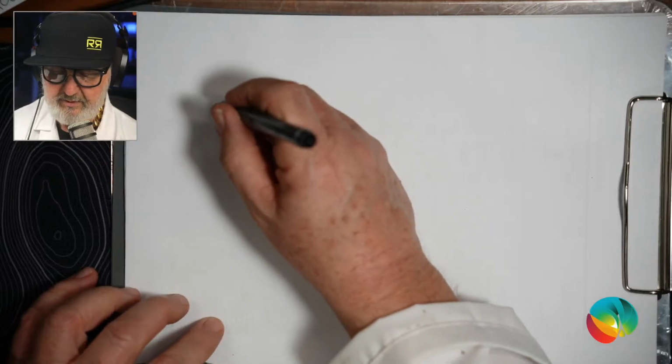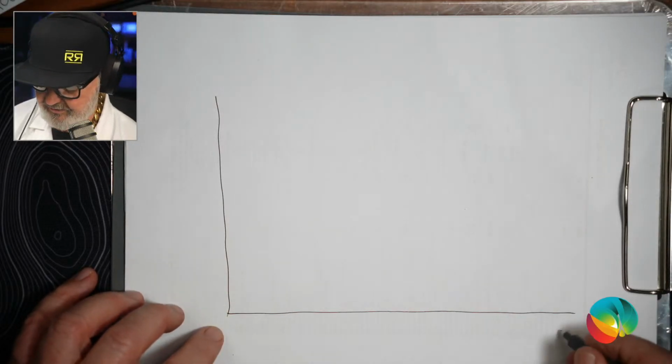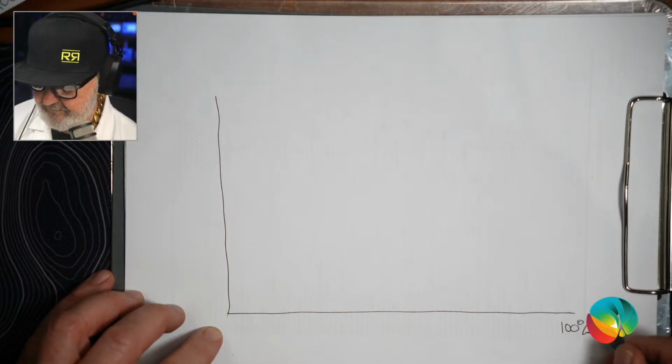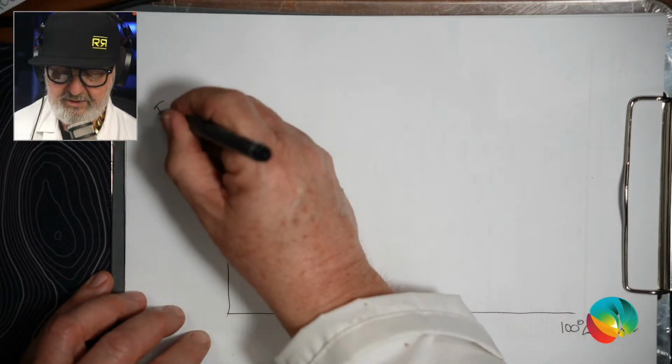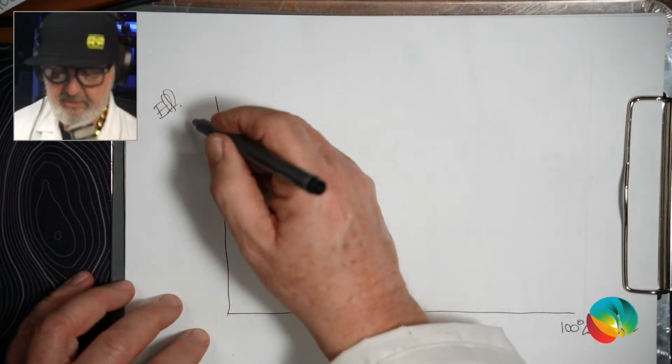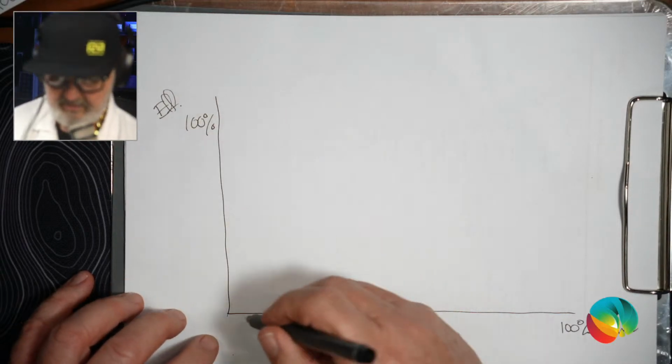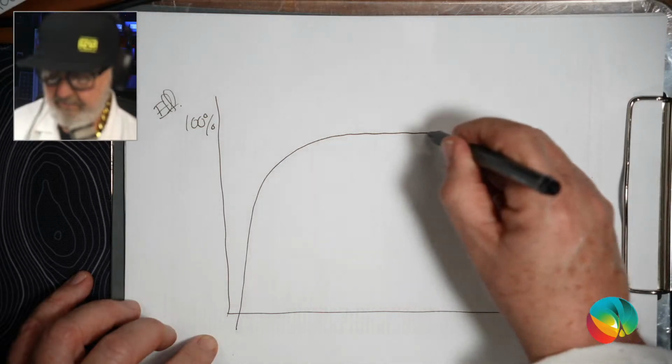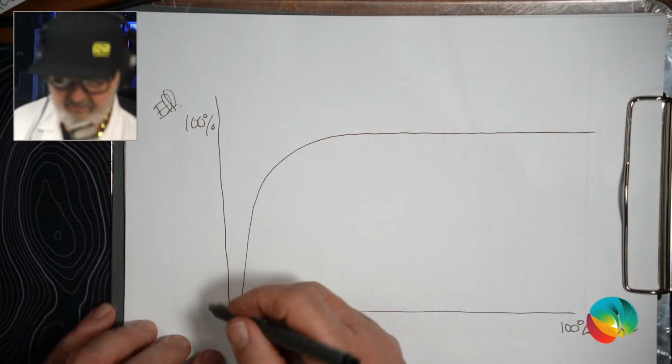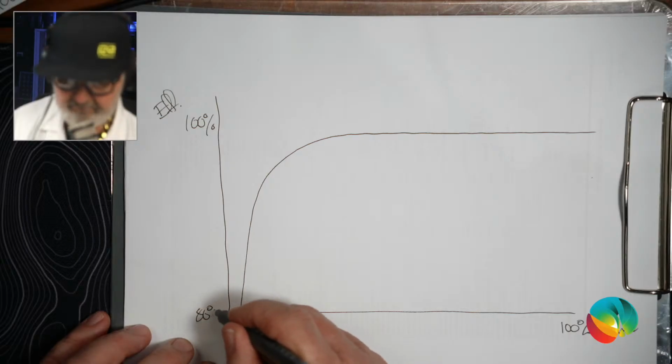So yeah, that's why long strings are good. In fact, generally solar inverters are more efficient the further up you go in the power curve. I haven't actually prepared a drawing for this, so I'll just have to do it myself. If I draw the power curve, and I'll do this in percentage. So that's 100% power. Okay, and this is efficiency on this side. And so we might be 100% efficient, and our power curve might look like this. And I'm probably starting here at something like 80%.